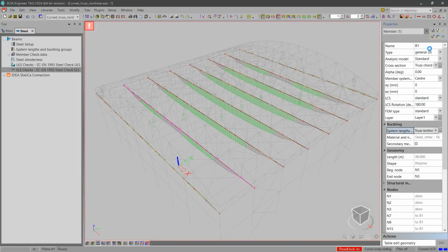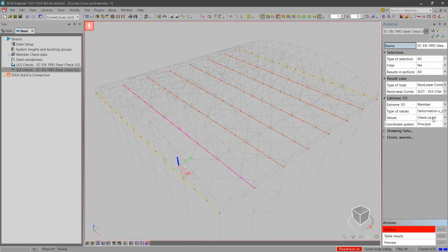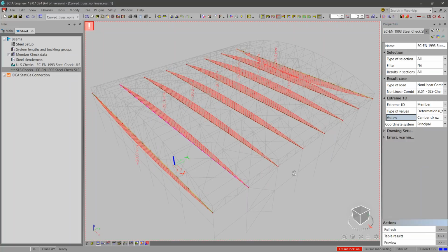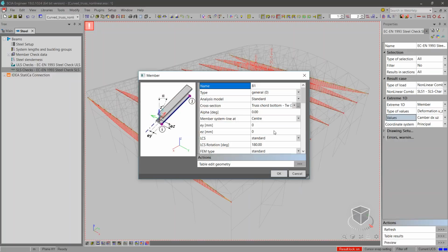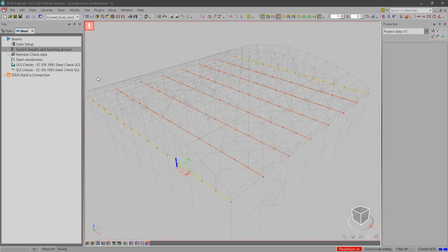-20. And now just to verify whether everything is correctly applied, I can show the camber value on screen. And so immediately I see that for some of the beams, I have the correct value. But in this case, I have LCS rotation. So these beams have a different section and their local axis is rotated. How to deal with that?